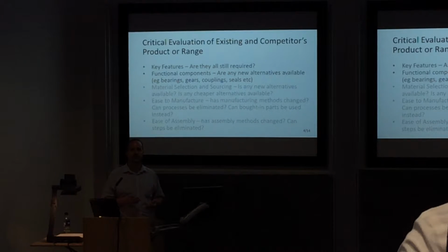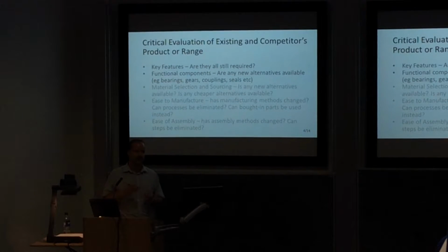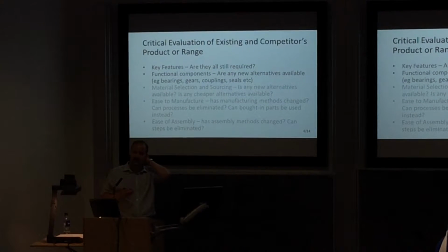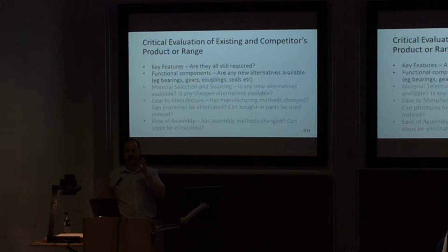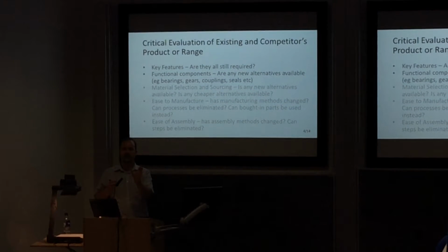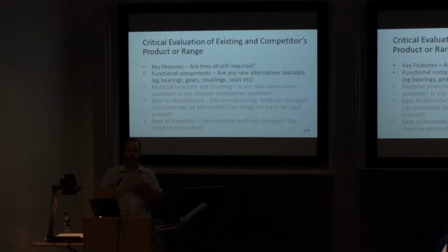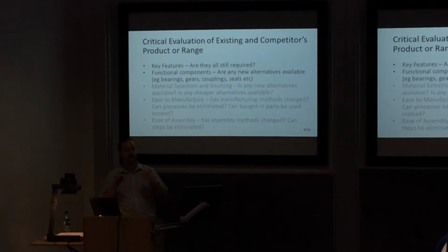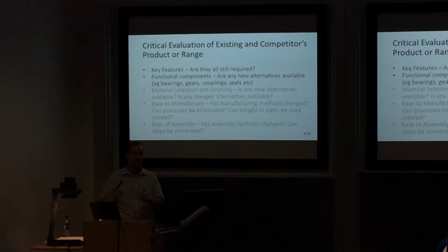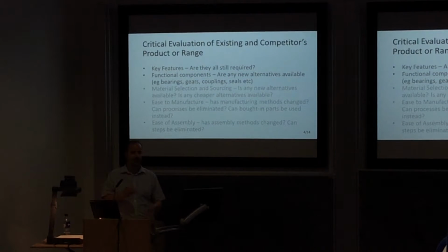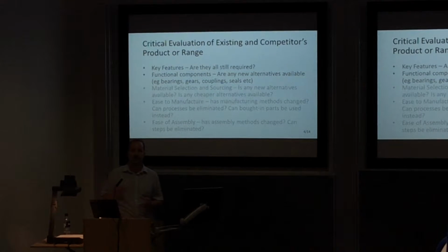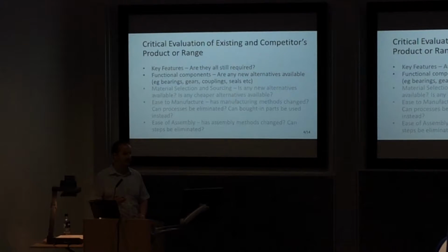We now have mechanical seals in place. Mechanical seals are smaller, they don't take up as much space, but there are still designs available on the market where you have an allowance or a large space within your seal envelope because it was originally designed to accommodate a packed gland. So we need to be able to review the designs and move with the times to ensure that we are not over-engineering to suit obsolete components or obsolete features.